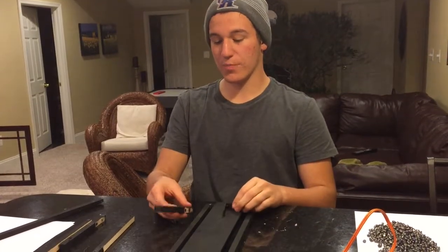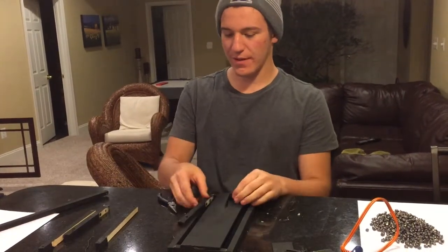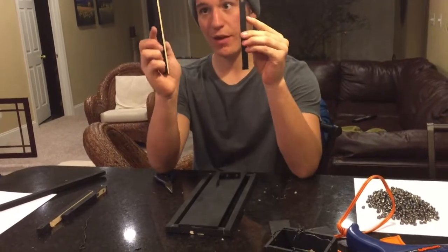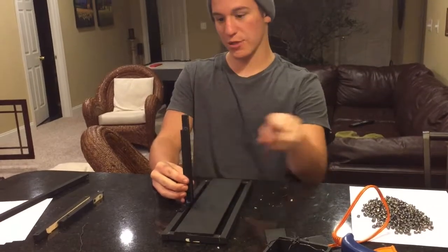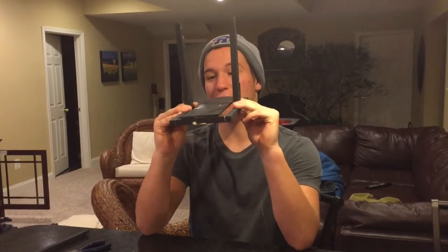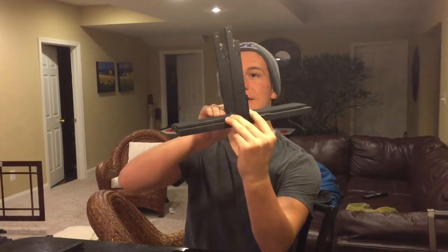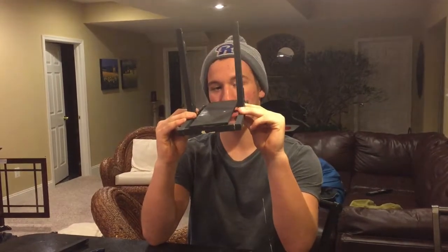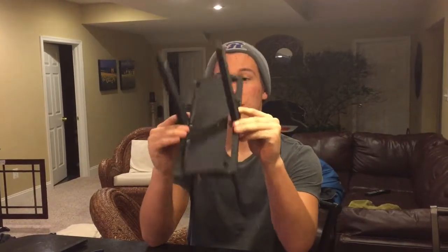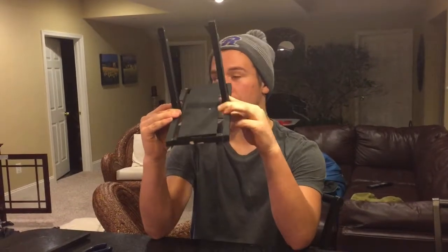Alright, now we're building the supports for our actual lever and pivot. So what you're going to do is take one of these and one of these, connect them together like that, and then put on one of these metal supports. Afterwards you're going to glue them onto the base of your trebuchet so that eventually we can attach our pivot. After you're done gluing everything together and attaching it to your base, you should end up with something like this. Of course, you're going to clean up all the glue on the sides and on the bottom, but it should be pretty straight. It should be at right angles, and you should be able to put your fulcrum in between the two.